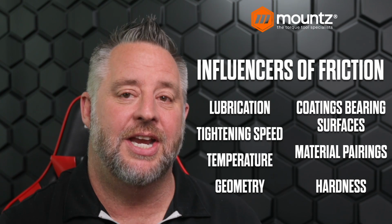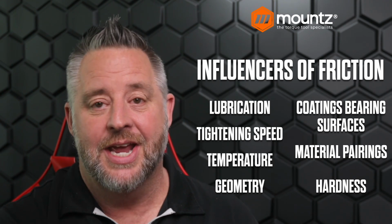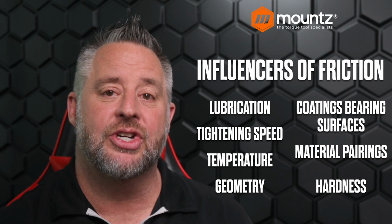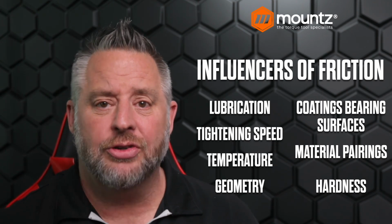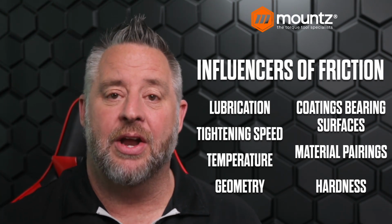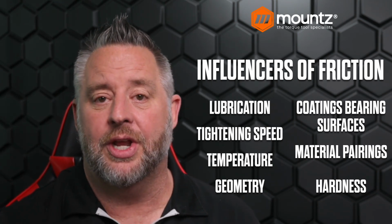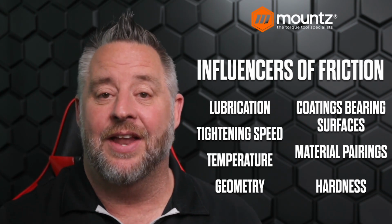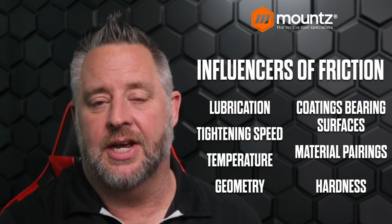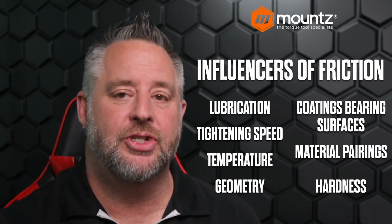The coatings on any bearing surfaces that may be happening. So if there is a material change in the part, that can influence the amount of friction. Also, tightening speed can cause changes in the amount of friction that is introduced, whether you're using a hand tool and it moves to a power tool, and that power tool runs at a very high RPM. That can heat the component, can cause issues that way. And that leads us into the temperature.